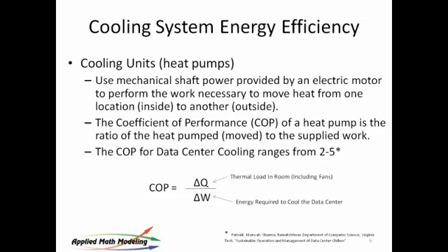Now, if it's a chilled water system and the water coming to your data center is also going to other parts of the building or the data center, things become a little more challenging, right? Because in this case, we're not looking at pure wattage, because the energy is being effectively distributed throughout the building or to other data centers. But I would still encourage you to measure the amount of energy going to the chiller and use some method of proportion. You can do it based on heat loads, for example.